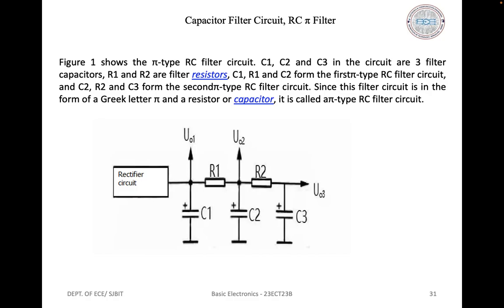So the figure shows the circuit, with capacitor C1 being the reservoir capacitor, and R1 and C2 the additional components. The combination of C1, R1 and C2 is referred to as a pi filter because of the pi-shaped arrangement of the circuit components. Assuming a constant output load current, the reservoir capacitor continues to charge.